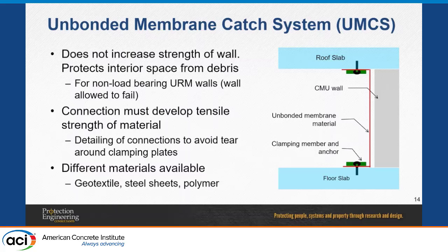Now, whenever we say work, it's always relative, right? Work for what? For what blast load? For what intensity? If you put a heavy blast load, obviously, whatever retrofit you put there, it's going to overload it. So always take it with a grain of salt when people say, oh, I have a blast retrofit. Well, yeah, blast retrofit for what type of walls, for what type of blast load, what intensity of blast load, what performance level?